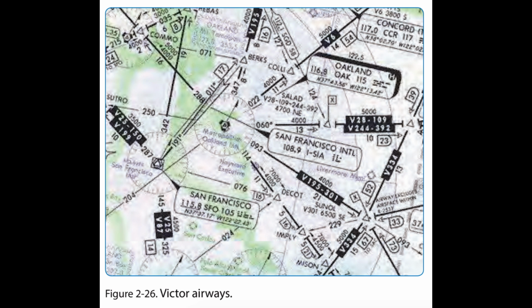Low-altitude RNAV-only routes are identified by the letter T prefix, followed by a 3-digit number, T200 to T500. RNAV routes are depicted in aeronautical blue, as well as the RNAV route data, which includes the following, figure 2.28. 1. Route line. 2. Identification boxes. 3. Mileages. 4. Waypoints. 5. Waypoint names. 6. Magnetic reference bearings. 7. MEAs. End of page 2-14.